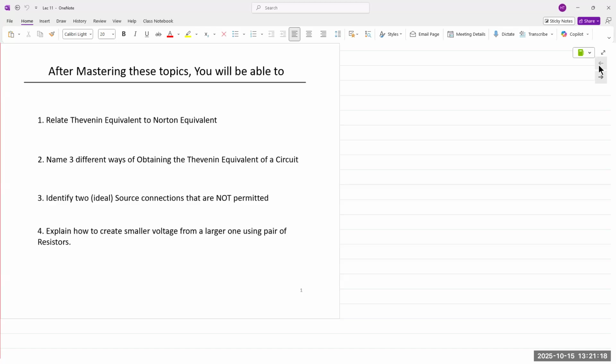So you have a large linear network comprising multiple sources and multiple resistors, could be hundreds, thousands, even millions of them. As long as it's comprised of linear elements, you could represent that entire circuit as one single voltage source in series with a resistance. That theorem came to be known as Thevenin's theorem. It's a very important concept in circuit analysis, and very useful when you're trying to reduce circuits, or create a sealed-box representation of a larger circuit.